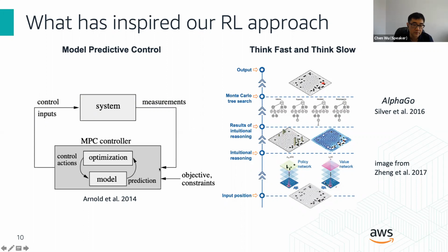So you observe, and then you come up with another 10 actions, and you only use the first action to interact with the system and discard the remaining 9 actions. I think that's quite an interesting way of combining optimization and reality. So that's model predictive control.